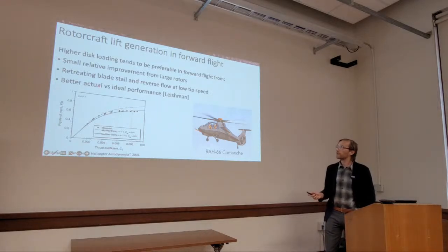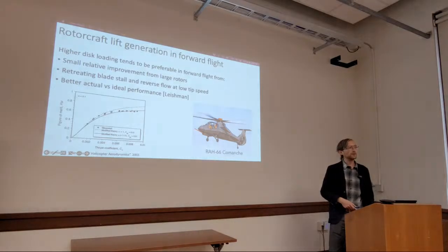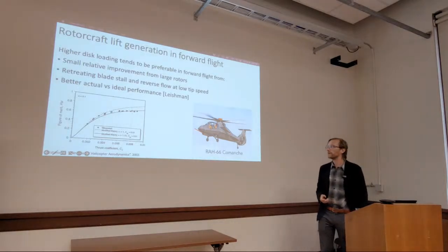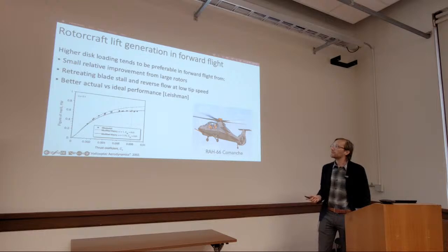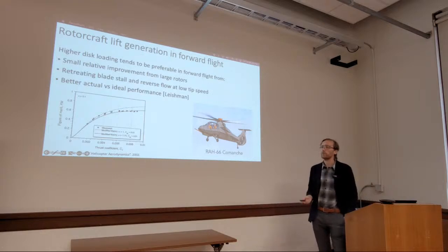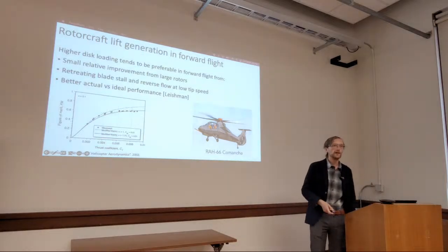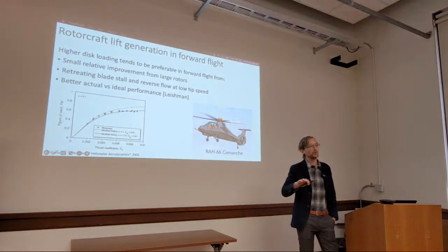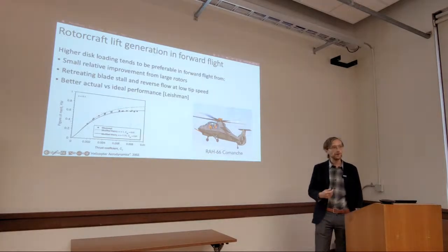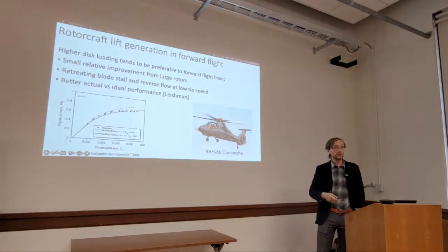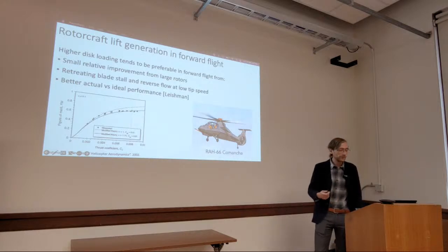Also, if we look at the actual versus ideal performance, ideal being the one given by momentum theory, we see from this plot that for higher disk loadings, which correlates with higher thrust coefficients, the actual performance is closer to the ideal one, and that is measured by the figure of merit. The figure of merit being defined as the ratio of actual rotor performance versus ideal performance. So with higher disk loading, the actual performance is closer to the ideal one, so that might be preferable as well.